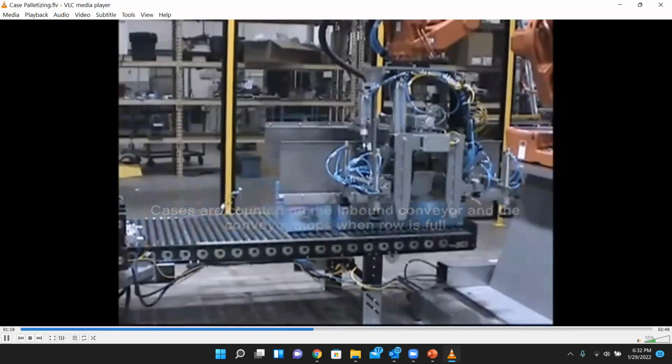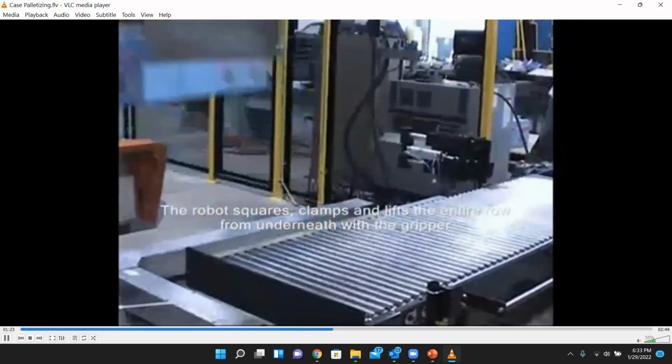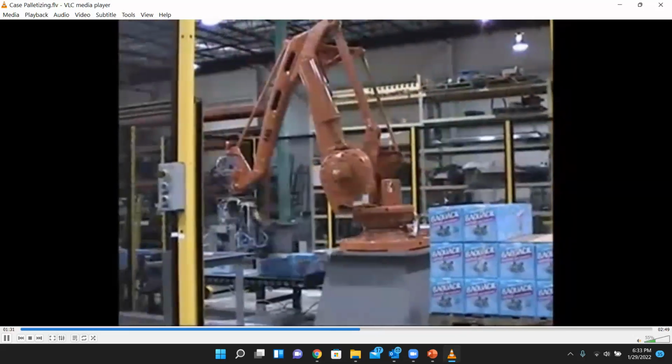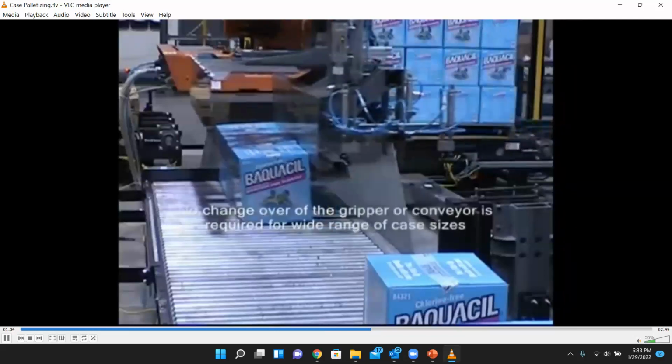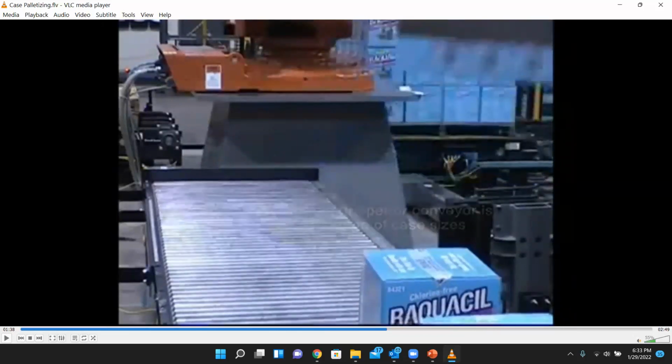And then on the conveyor line, you get the items. Whatever item, in boxes. So maybe the same manipulator with a different end effector on a side, you can use for this one. It stacks on the pallet. So you can see that manipulator end effector has two sides. One side to handle the boxes, the other side with the suction cups to lift the board and place it on the pallet.